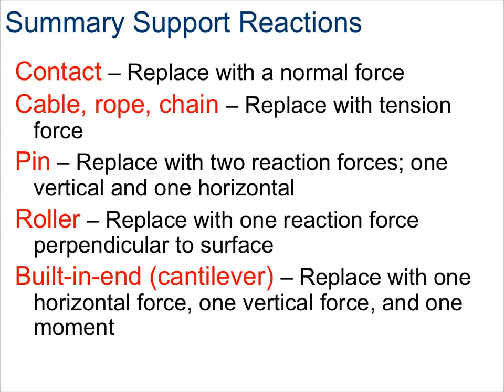So to do a summary of the support reactions that we looked at today, anytime there's contact between objects, we're going to replace that with the normal force. Remember, the normal force is the force that's holding the object from falling. Anytime you use a cable, rope, or chain, you're going to replace it with a tension force. Anytime you have a pin support, you're going to replace it with two reactionary forces, one in both the horizontal and vertical directions. With a roller support, we're going to replace it with one reactionary force, and it's always perpendicular to the surface. And finally, with the built-in cantilever, we're going to replace it with a horizontal force, a vertical force, as well as one moment.